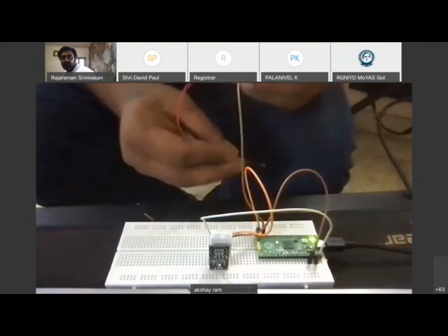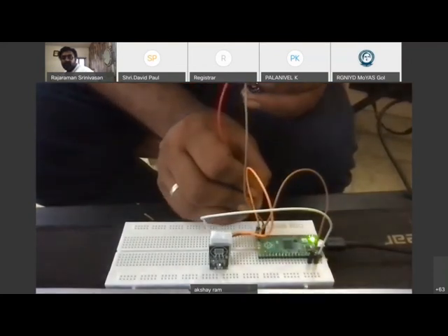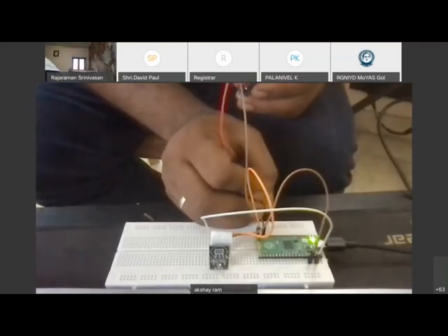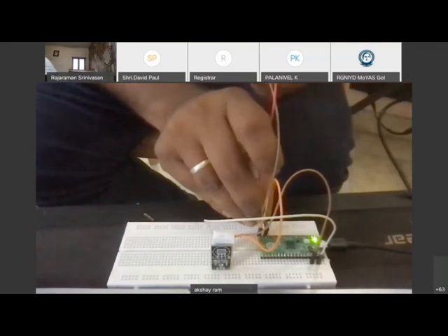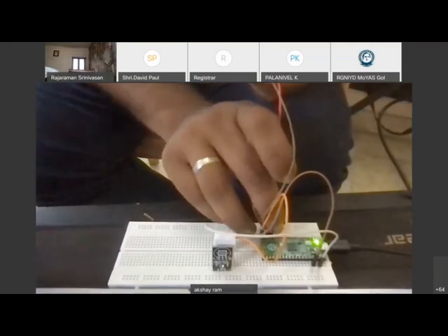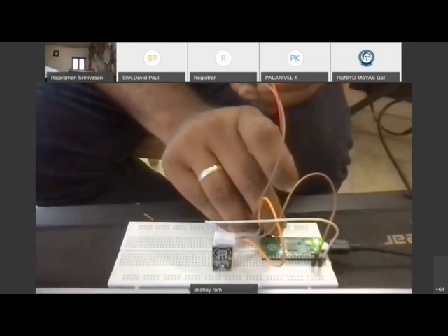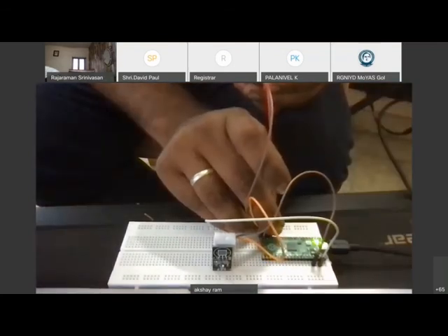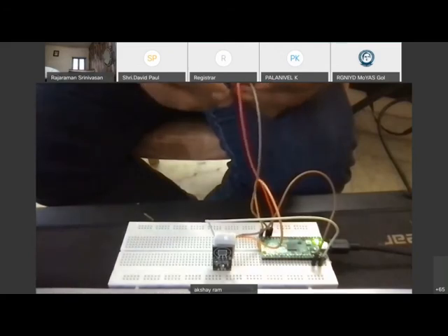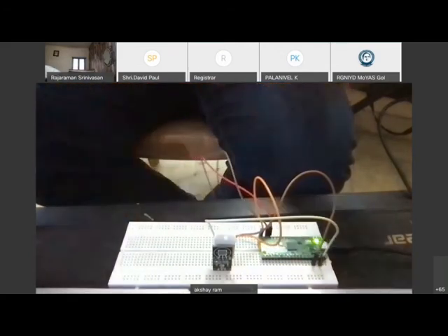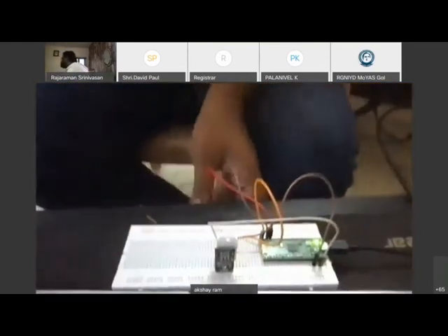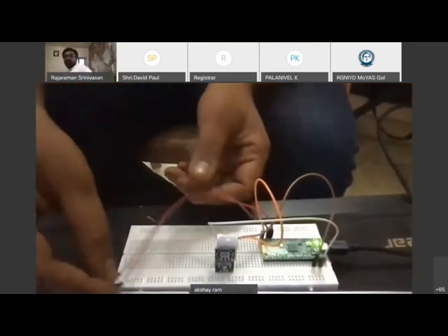And then we would just connect this over to which pin? Anything is okay. 16, I think 13 is good. So right next to it, I'm using GP13 as the positive, and the earthing below that for grounding. So the buzzer, it's just hanging.